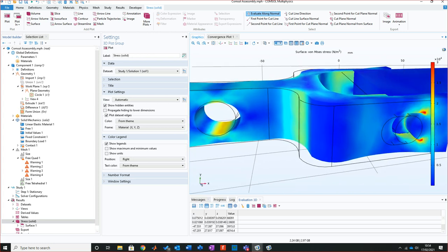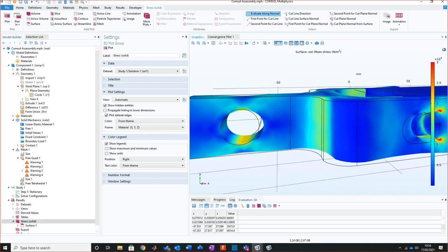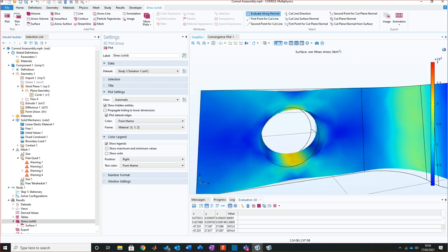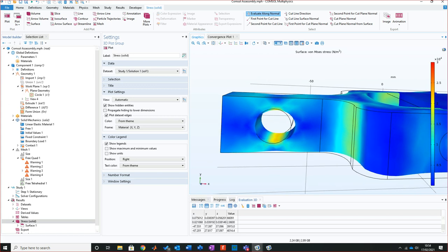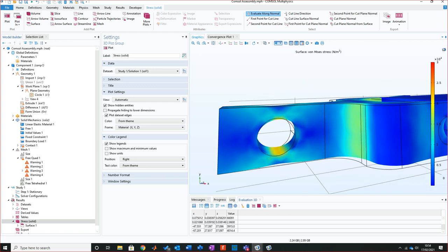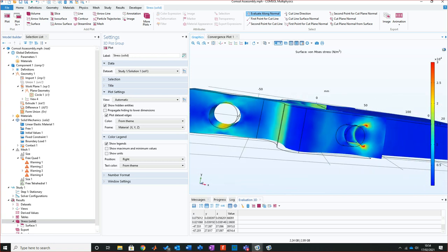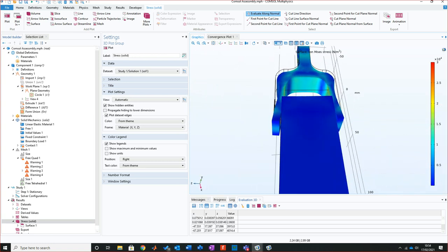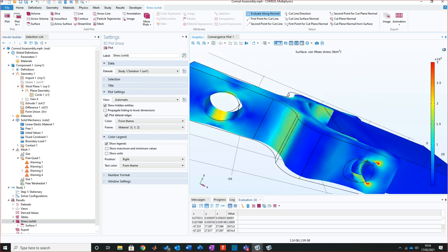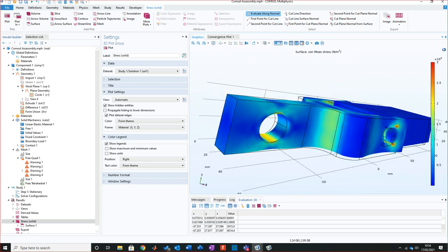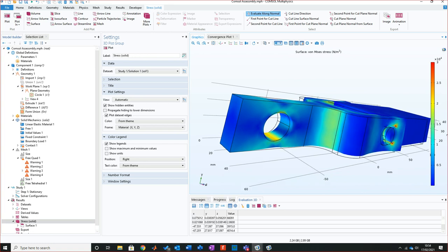This would be fine if you weren't conscious of deflection. So if you were saying that we don't care if deflection is increased, it would be fine. But if you are conscious, so if you're in a precision engineering job, for components, things like that, this would be a problem. This is where you may want to triangulate a little bit more. So obviously with some things you can't just simply say, let's let it move more. In this case, we've had to really consider how much it moves.